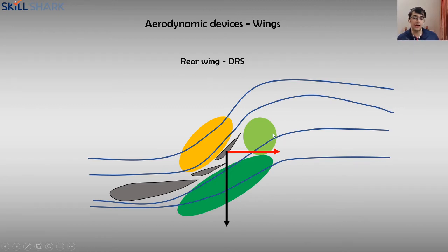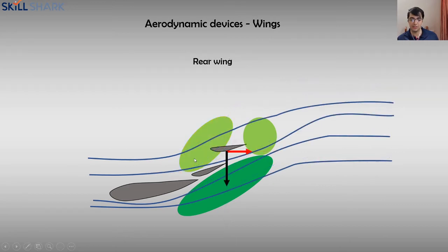So F1 cars, and also if I'm not mistaken, LMP1 cars, do have something called DRS, where they open one of the flaps of the wings, thereby reducing the drag. If you open that wing flap, it makes for more smooth airflow through this little gap over here. Obviously the pressure decreases here because it's running a lot smoother at higher velocities, and the pressure differential is also less. It still will be there, of course, because these elements still have drag, but this element has very minimal drag. You reduce the effective drag on the rear wing, and teams use this to their advantage.